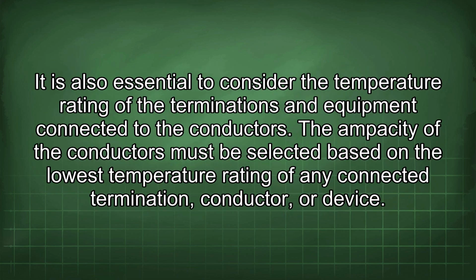It is also essential to consider the temperature rating of the terminations and equipment connected to the conductors. The ampacity of the conductors must be selected based on the lowest temperature rating of any connected termination, conductor, or device.